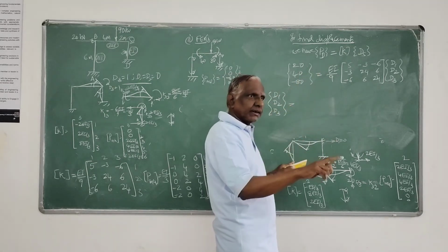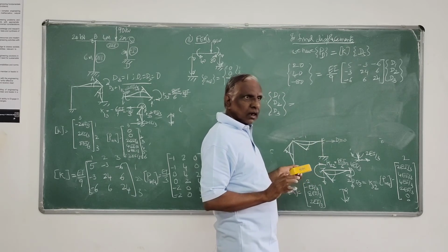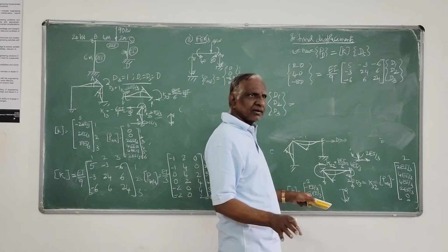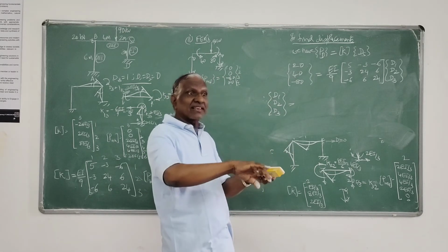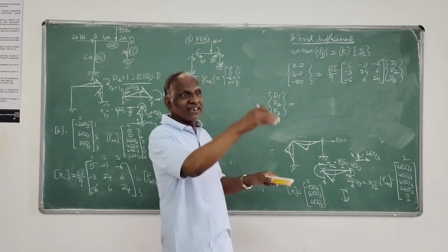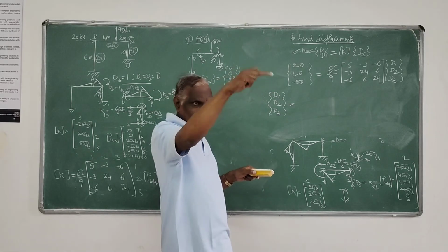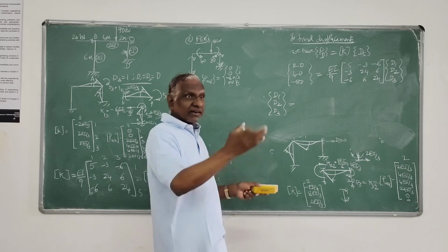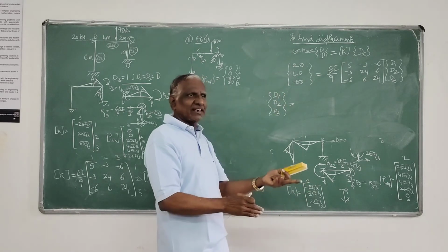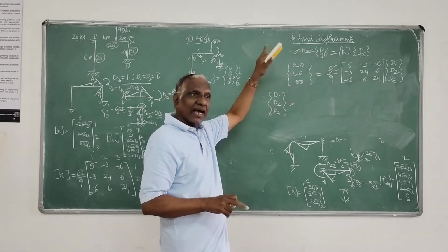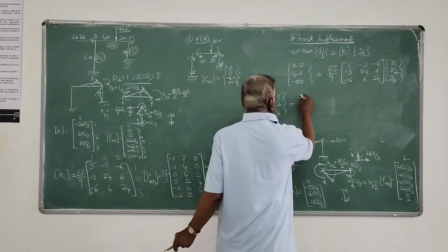This is nothing but joint load minus the reverse of member load. The joint loads are always in translation only. The joint load is acting at the joint itself, so you need not reverse its sign, whereas the member load is acting on the member and the fixed end moment is reversing that. Again, we have to bring it back to the original direction. That's why in that overhang problem, we took the moment due to the load directly as joint load. We didn't reverse it. In fixed end moment, we are reversing its sign, taking the reaction of the action. That's why here, having found the actual applied load, we have to reverse it again. We have to take it back to the original. That's the thing you have to be careful about.